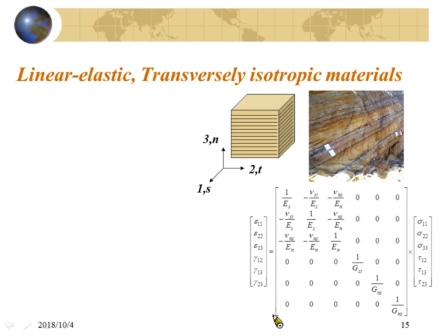You have a symmetrical plane, and the symmetrical plane will be isotropic. So the relation between Young's modulus, shear modulus, and the Poisson ratio at that plane can be clearly defined. They have a single relation. If you have a single relation, then you will reduce one independent elastic constant.